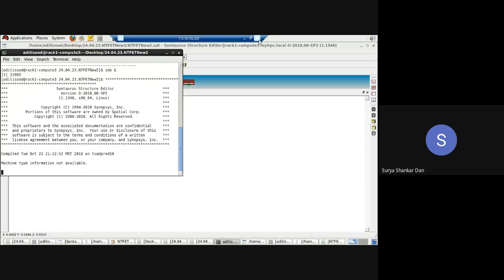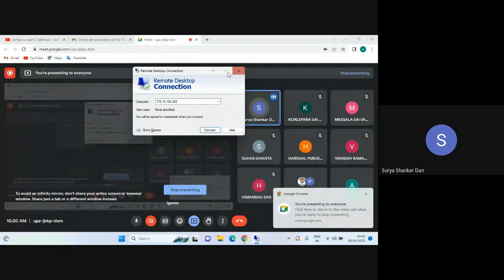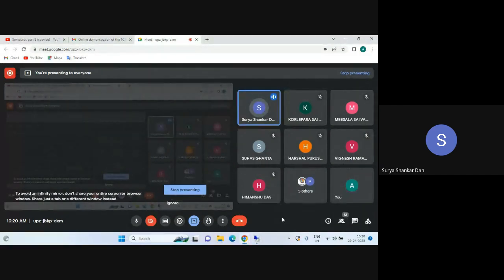So you have got the brief overview of how to do the simulations, and after the NSEM is over, I'm going to call the RP students, and we will have a meeting with Aditi, myself, and all the students, and essentially we will give you the device and the CMD file. Individually, each one of you is going to take care of one parameter of the device. One of you will vary the oxide thickness. One of you will vary the source channel length, structure, dimension. One of you will vary the doping level.